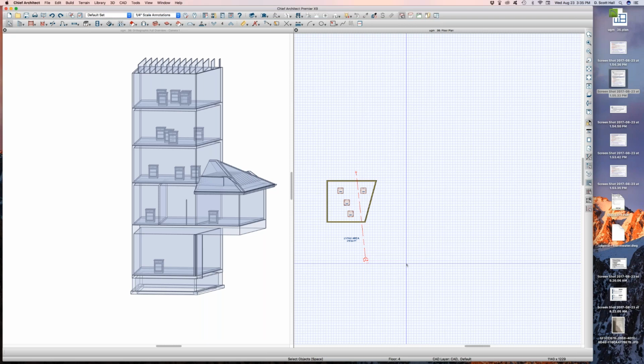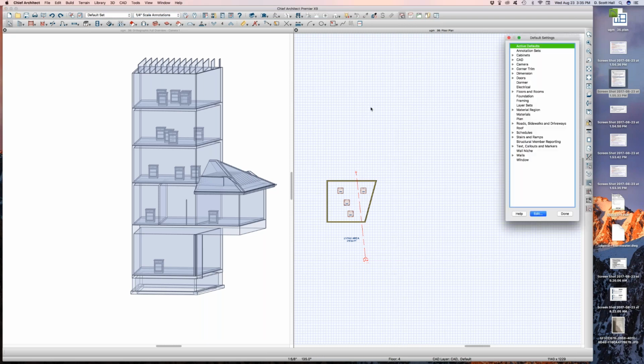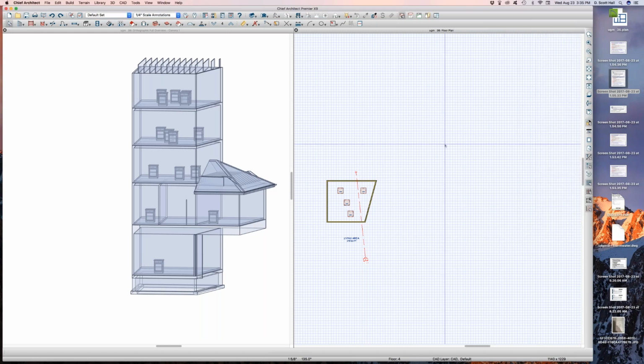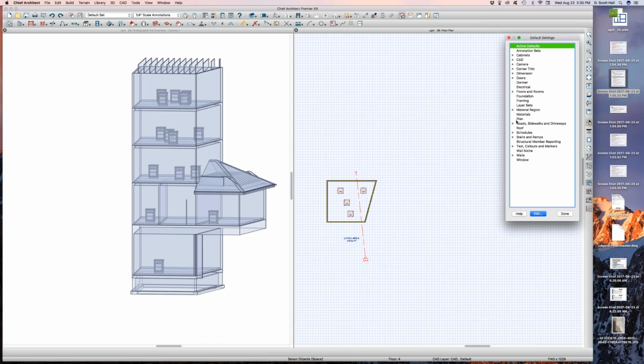Yeah. But if you're doing this like a 4-story building, so you're saying if you wanted to build a 4-story building, whether or not each floor is consistent with each other and it's just stacked, you set all your floors, set all your defaults, and then start laying in your wall structure. I mean, that's what it sounds like. So if you had a 4-story building and you wanted to affect the 2nd-story joist depth without affecting anything else, you would have to make that corresponding adjustment starting with the top floor all the way down. Is that a true statement?